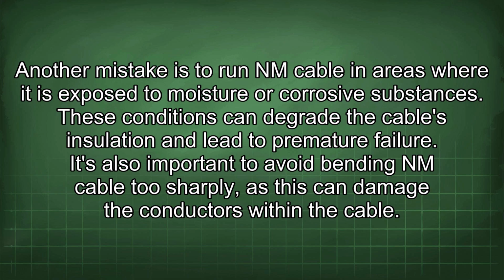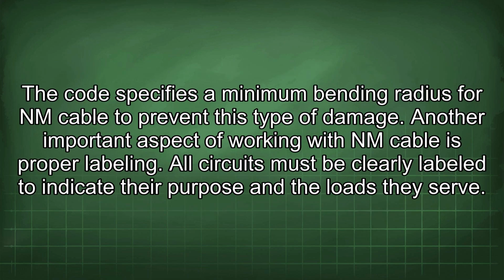It's also important to avoid bending NM cable too sharply, as this can damage the conductors within the cable. The code specifies a minimum bending radius for NM cable to prevent this type of damage. Another important aspect of working with NM cable is proper labeling.